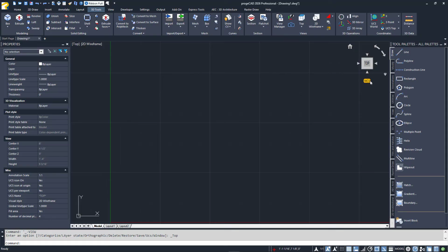The icon at the bottom that reads WCS allows quick access to any custom user coordinate systems you may have, or the orthographic projections as we saw in the Viewport tools. The two curved arrows will rotate your view 90 degrees from the current Z-axis. And finally, in the middle, the cube has arrows around the edges which provide quick access to the back, front, and sides.